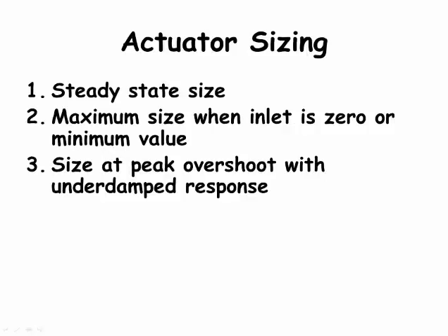One method is to base the actuator on the steady-state conditions. For the fluid heater system, the steady-state heat input was calculated to be 828 watts on page 23-1 of the course packet. Would you choose a relay that had a maximum allowed load of 850 watts based on the steady-state value?